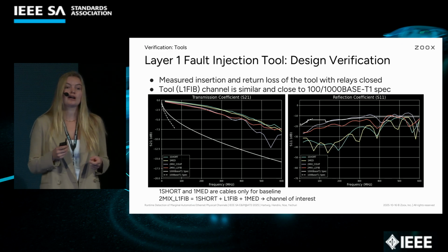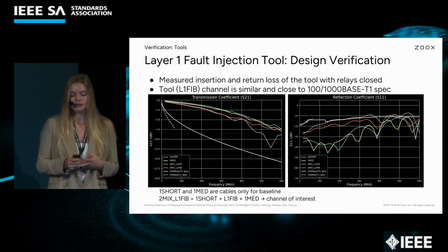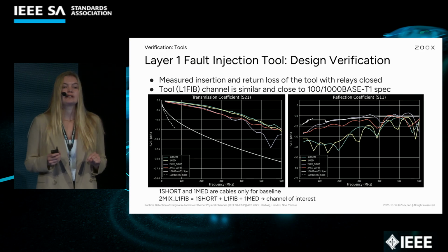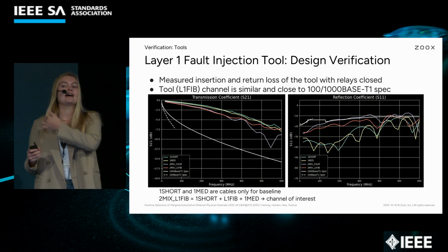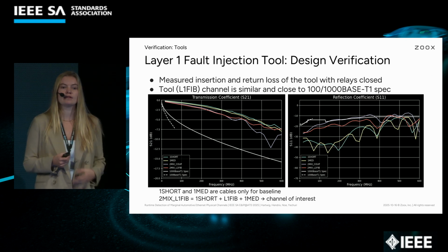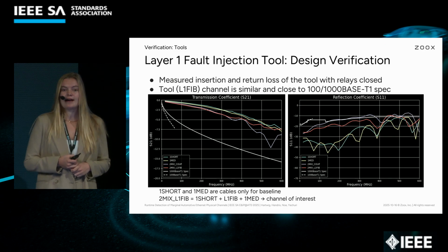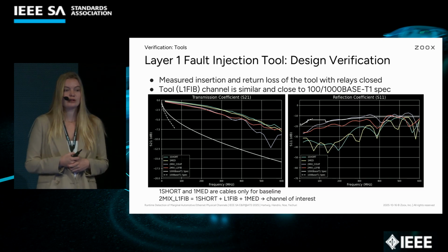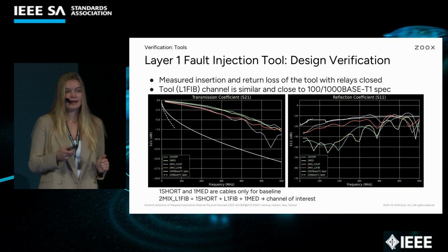Whereas our reference coupler as well as our fault injector board, pictured in red, show some minor deviations, a slight excess of the Ethernet spec. While this is not ideal for return loss, we will only be using these tools on stationary test assets, so we decided that for our purposes, this was adequate.